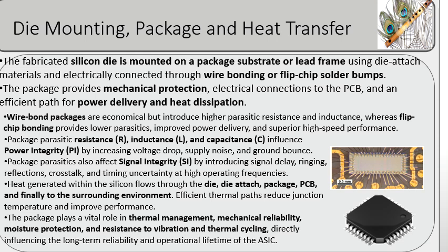Besides carrying power and signals, the package also provides the primary path for removing the heat generated within the chip. The choice of packaging technology influences electrical parasitics, thermal resistance, power delivery capability, and high-speed performance. A well-designed low thermal resistance package is therefore essential for achieving efficient cooling, reliable operation, and long-term ASIC performance.